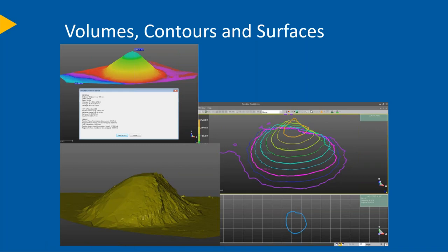But quite good. I actually had an argument in the office the other day between two people over whether scanning or using a GPS or total station would be faster and more effective in capturing volumes. Both convinced their workflows were the best. I tend to think that the scanning would probably win, and that you can do just a couple of scans, probably only a minute or two each, and get all the data you need to create a very accurate volume, and also much safer in that nobody actually has to get on the stockpiles and have risk.